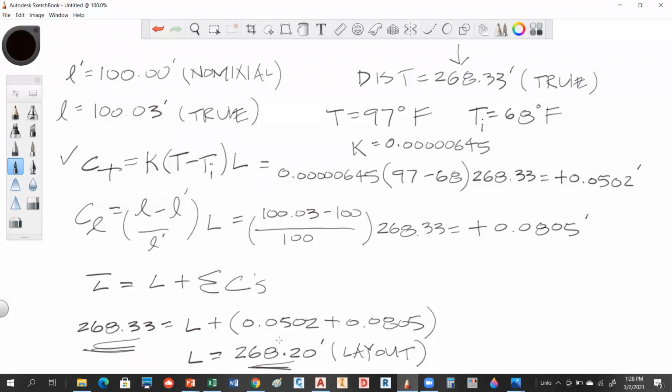Let me ask this hypothetically. What would you use in an EDM? So you shot a distance with an EDM. Would you have to do this stuff with an EDM? No, because the errors would be different. It would be instrumental. Well, there are natural errors. Oh, and then laying out of the prism. Well, this we wouldn't have a problem with at all, right? In an EDM, that one would not exist.